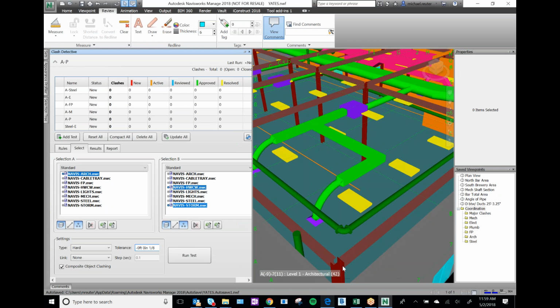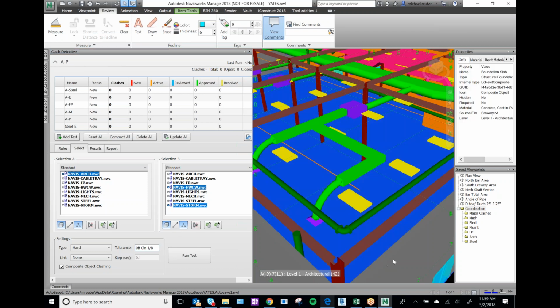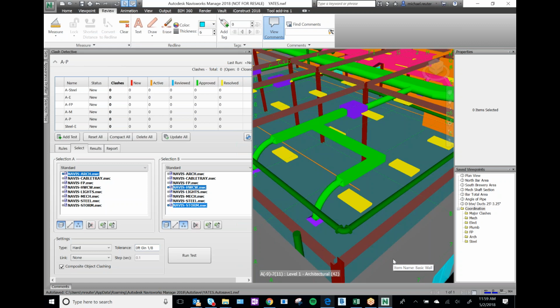Well, you need to account for that in your model, but you can't. They're not going to model it, so you've got to account for it somehow. So if you add tolerance to it, then that's how. Okay. So if 2 inches of SFRM are supposed to go around the steel, then you put a tolerance of 2 inches. Then it'll account for it.